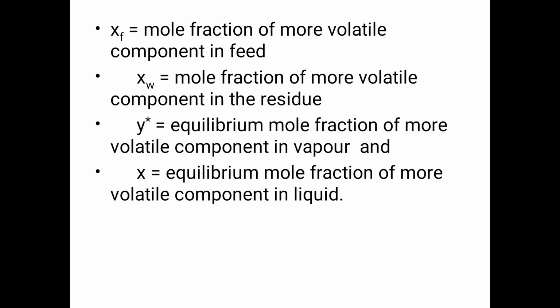And xW is also the mole fraction of more volatile component, in the residue collected in the round bottom flask, that is, the mole fraction of more volatile component in the residue phase. y star is the equilibrium mole fraction of more volatile component in vapor, and x means the equilibrium mole fraction of more volatile component in liquid.